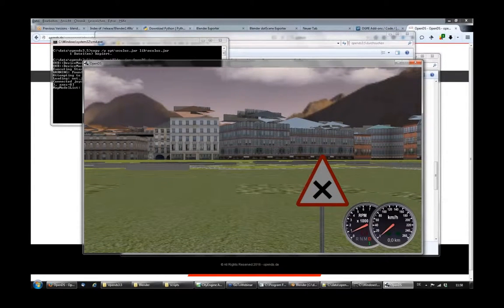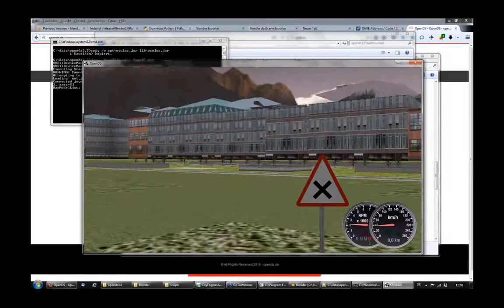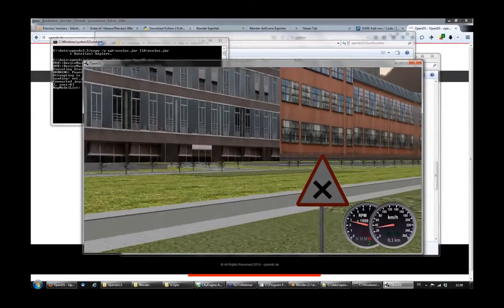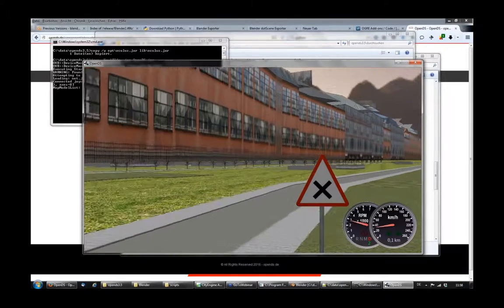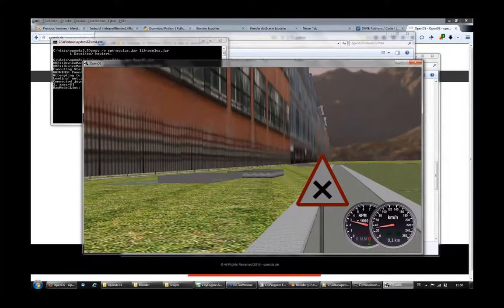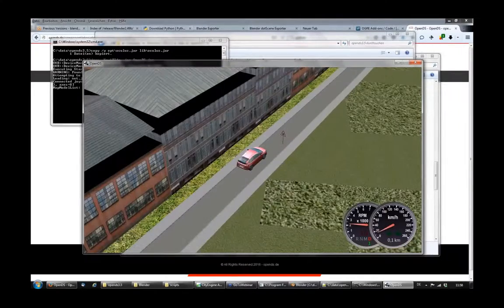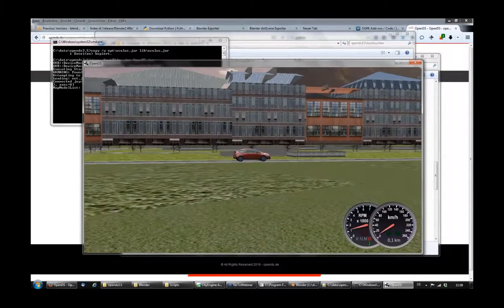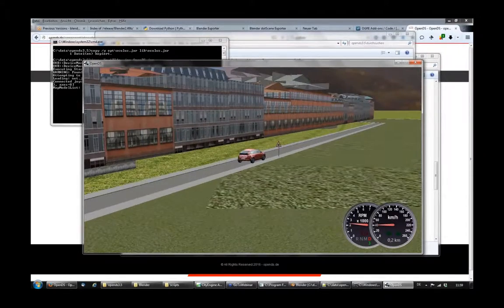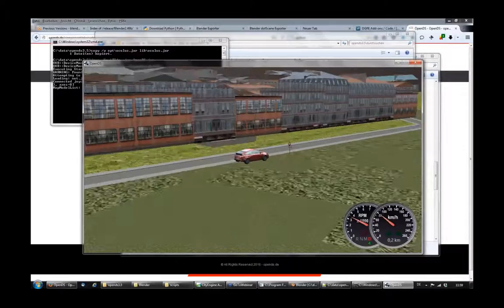And the textures are there. That issue is solved. Now I want to get closer to the map. You can see there's a problem with the correct height of the buildings. You can drive under them, as they're placed slightly too high. So this is an issue that needs to be solved in the CityEngine before you export your model.